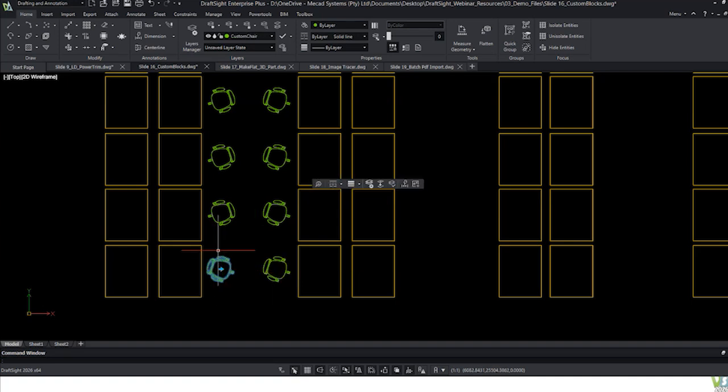The nice thing with edit, as I mentioned about multiple configurations, is you can have this chair facing 90 degrees, 45 degrees, 30 degrees, etc. So you can build your configurations in such a way that, if the desk has to change, you can ensure that your chair is facing the desk at the correct angle. This is just an example with chairs, but for anything else you can do the same. Have your block, give it configurations, and then reuse the configurations inside your environment.